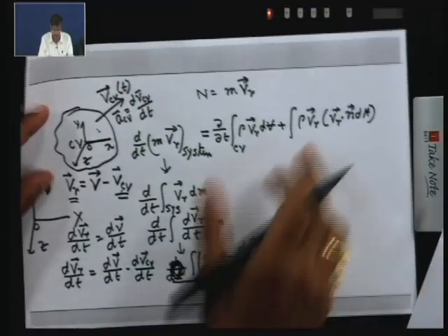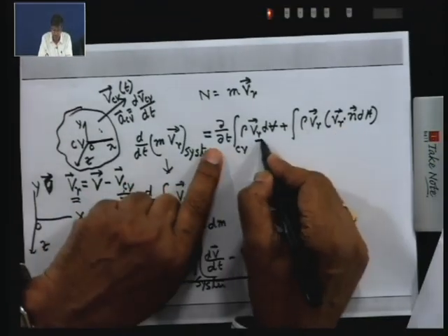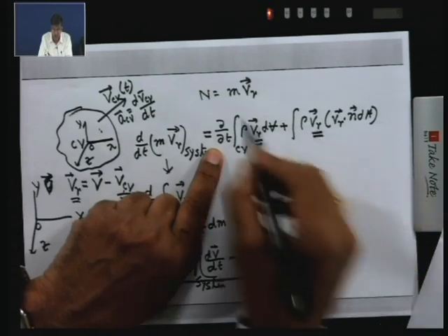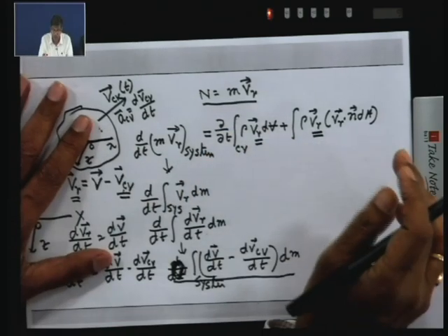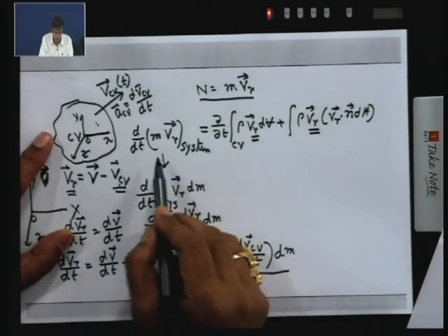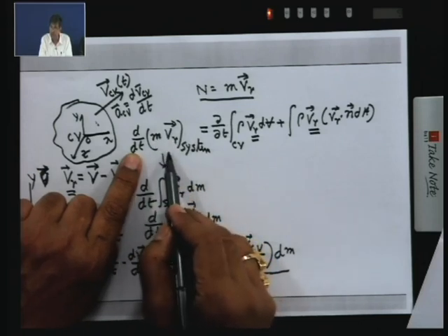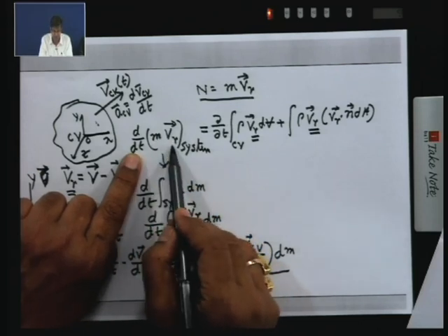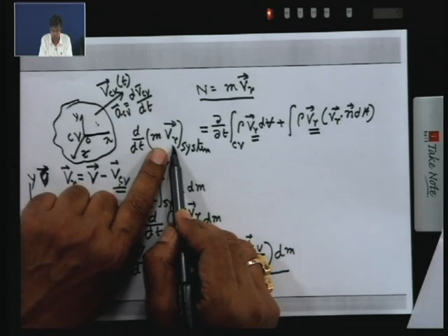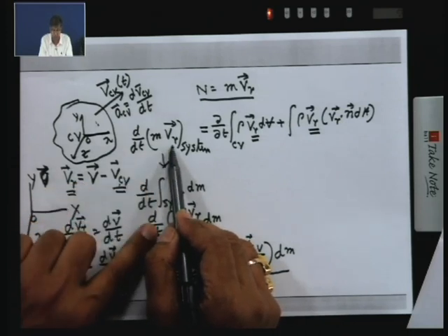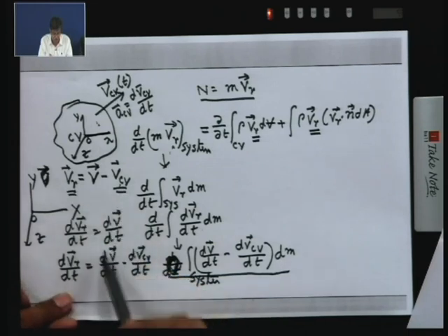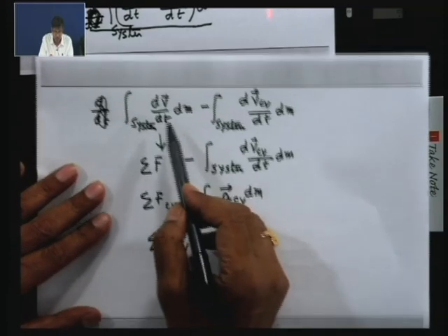left hand term. That means in the right hand term we just replace the absolute velocity with the relative velocity, since we define the momentum based on the relative velocity. But when we do this, on the left hand side we cannot replace by external forces by Newton's second law, since the velocity of the momentum is not described in an inertial frame of reference. So, therefore, we have to substitute this where dV_CV/dt is not 0, which is the acceleration of the control volume, and there the left hand side gets a change, this minus this.